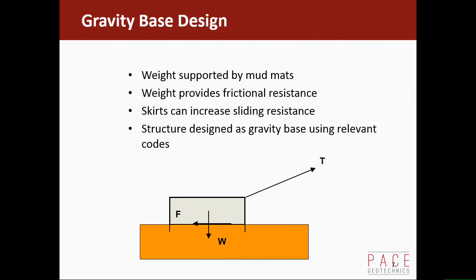And if it's a tieback anchor, we still use the sort of standard codes. Okay, so in this case that's drawing the sort of tieback anchor where you've got your line tension and you're relying on the weight there, and your shear at that interface is giving you your sliding resistance plus a little bit for the skirts there. Okay,